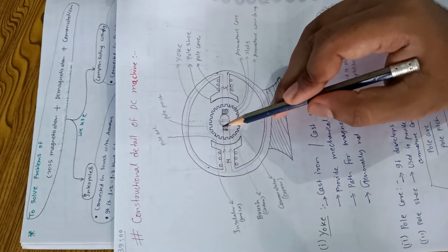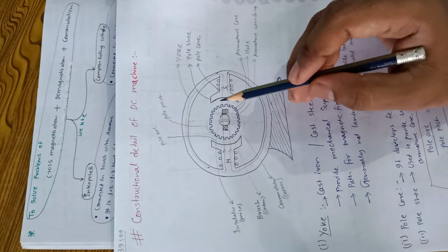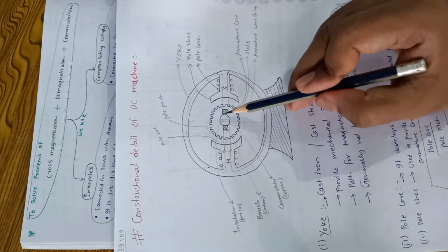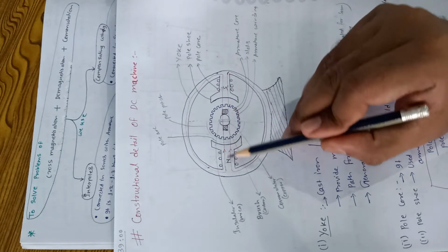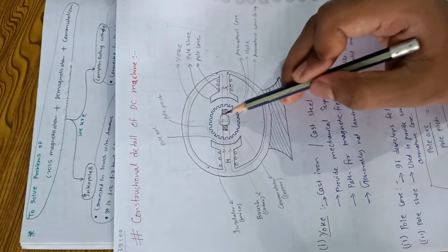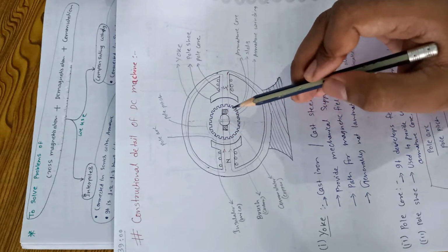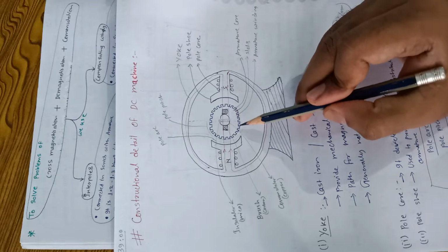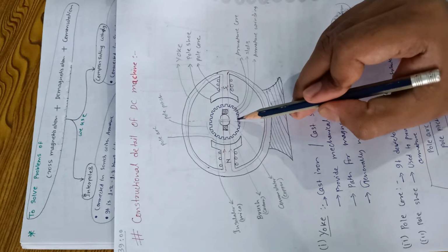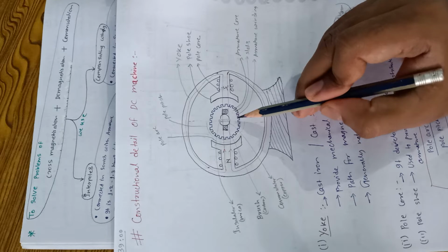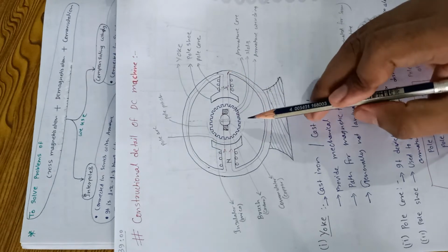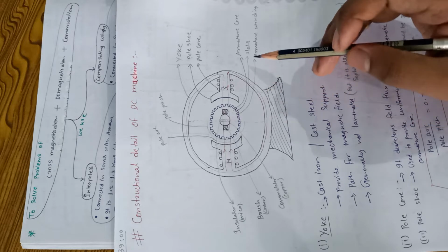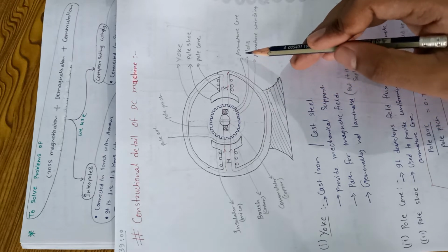Due to this current in the armature coil, armature flux will be produced, and we already have the field flux. Due to the interaction of field flux and armature flux, an electromagnetic torque is produced that will oppose the prime mover torque of this generator. So in this way we understood: first we generated EMF, and we connected the load.